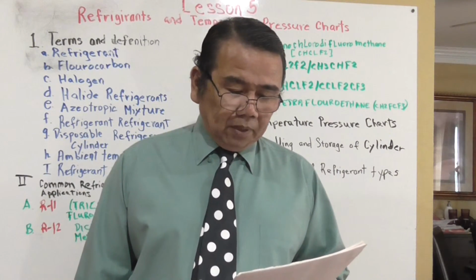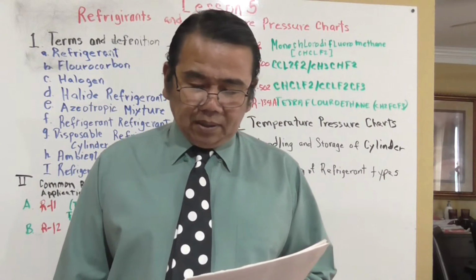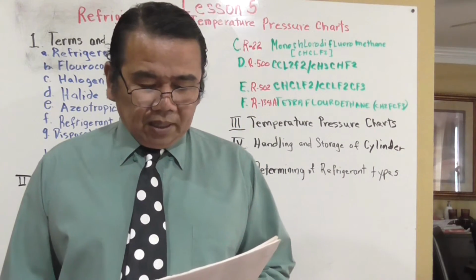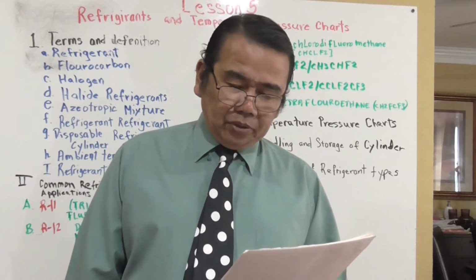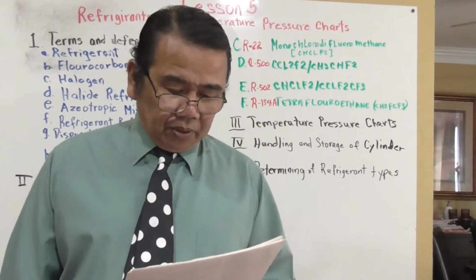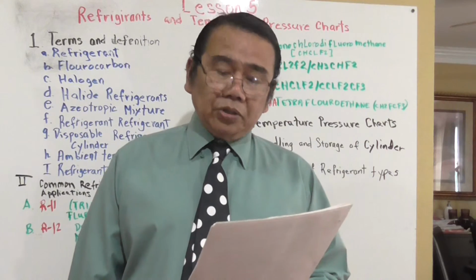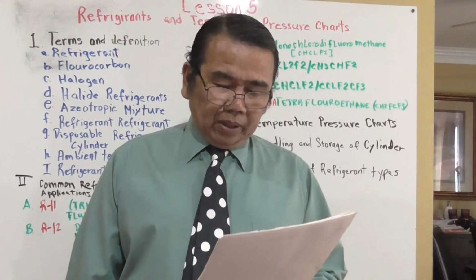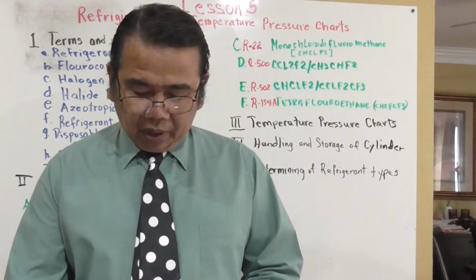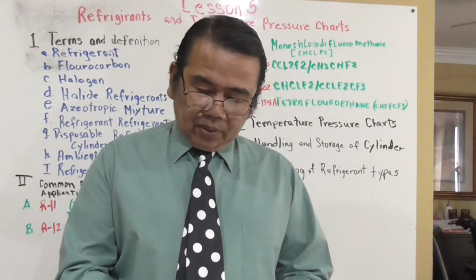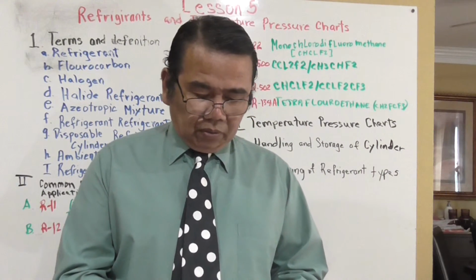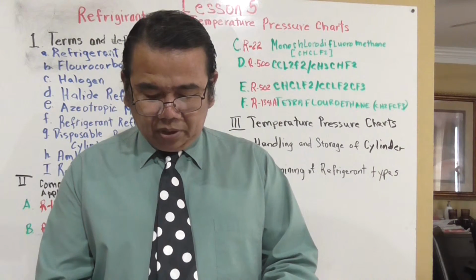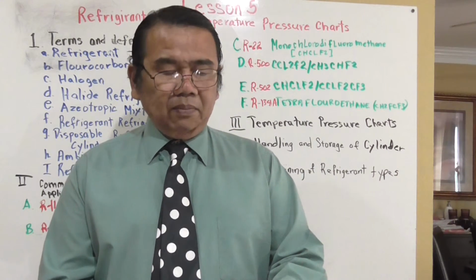By components application, the type of components can sometimes tell you the type of refrigerant used. Application: low temperature, medium temperature, or high temperature. The gauge pressure and the ambient temperature. By using the pressure and temperature relationship chart, you can determine the refrigerant used with the system off.